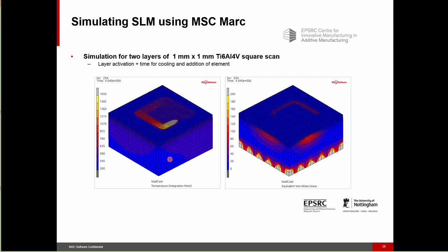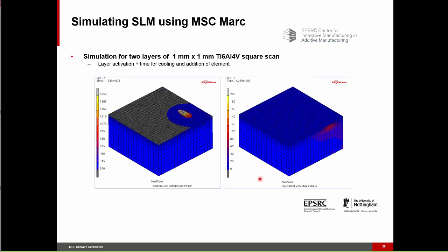And the thing I really want to point out is that we can capture the thermal behavior. We get a non-symmetric behavior because some material is solidified, on the other side it's not. And we can predict the stresses and the residual stresses, and you'll notice the high stresses are really where we have the constraints in the system.